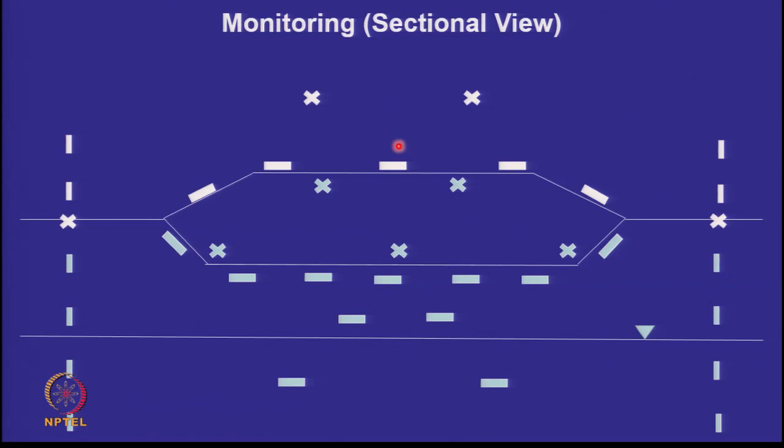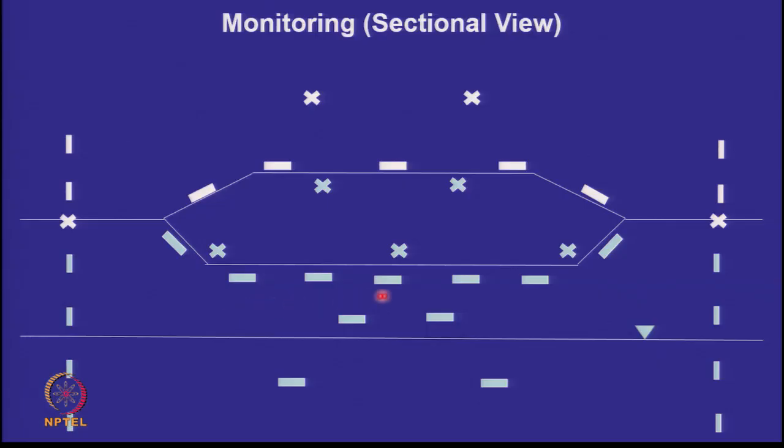We looked at monitoring, how we are monitoring beneath the landfill, above the landfill, at the boundaries of the landfill, so that we detect early. And one of the philosophical thoughts was, if you are very keen that we should detect leakages early, we might have to have a double liner system, because that was the only system through which you can actually know that leakage has occurred at a point. Otherwise, even if you put a lot of sensors beneath, you will not be able to detect early, because your leachate could leak from another point.